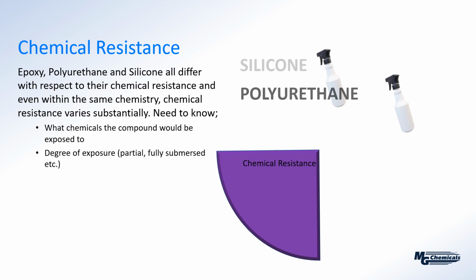That's not universally true, but for the most part, it's true. And then again, for the epoxy, we hit it with the solvent, and what we find is that generally epoxies outperform the two chemistries. So again, everything's sort of stacked relative to one another, and it's not absolute. There are exceptions, but more or less, if someone says, I need extreme chemical resistance, we're going to consider epoxy first off.